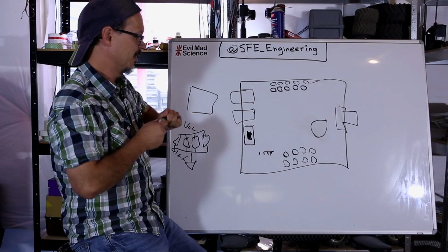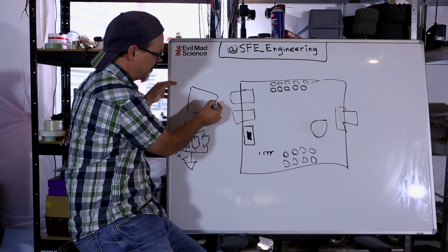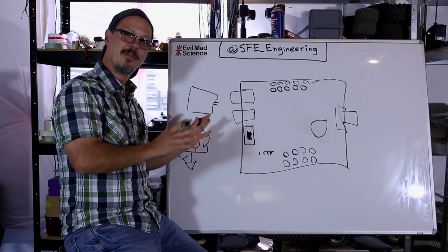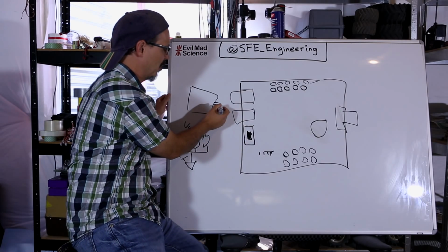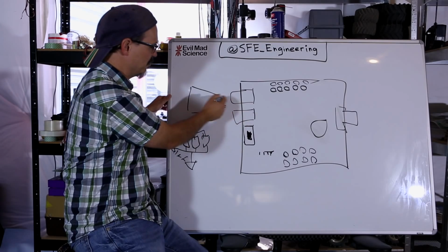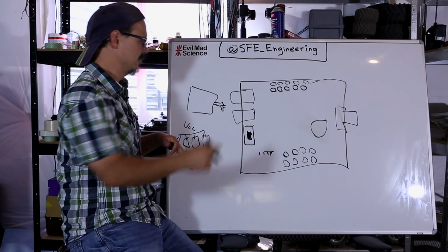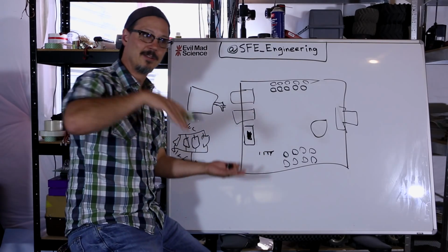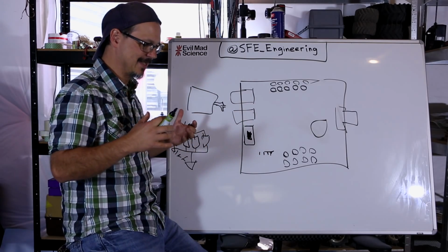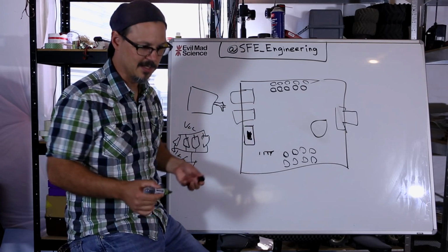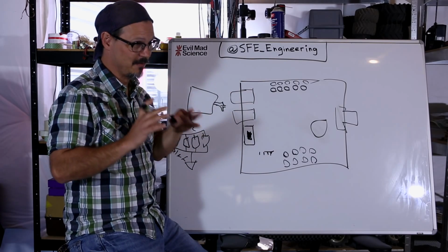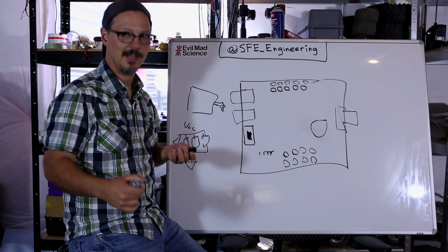A microcontroller, if you look at the pins, every time you see a power pin on this thing, there's going to be a ground pin really, really close to that power pin. And the reason is because they want you to put a cap right there, right? That is to minimize the length of those traces and to decouple noise on the power supply to ground. So it's important to keep components that are related to a certain circuit section close to each other. You want to keep those traces short and elegant and nice.